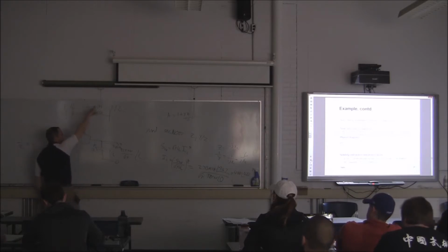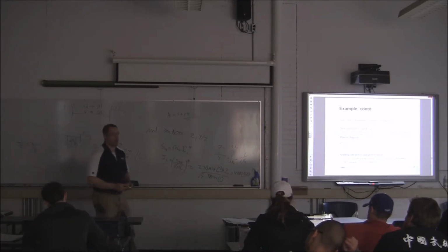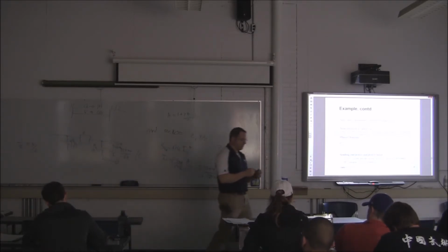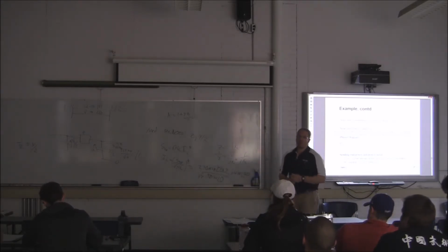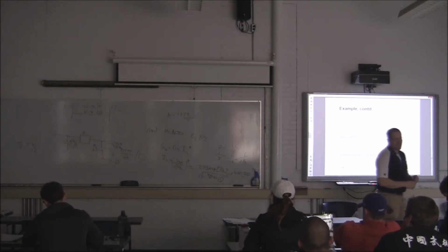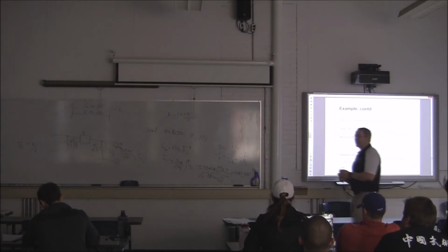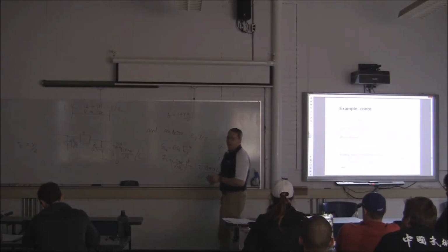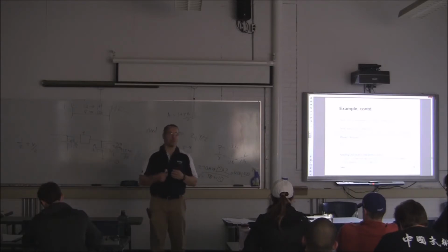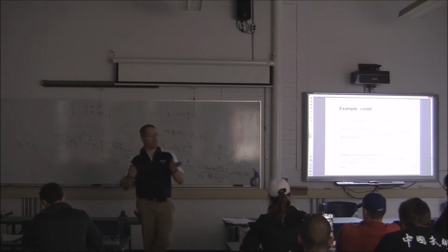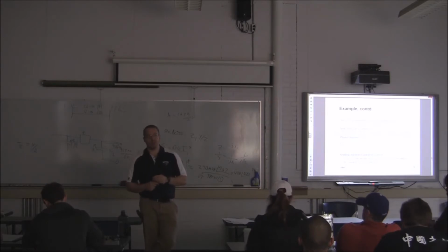So if this angle theta is higher than this angle, then what does that mean? Real power flow is from the higher angle to the lower angle. And that's the case when your X over R ratio is sufficiently high in your system, which almost all real world power systems have. So I could look at a diagram with bunches of voltages on it, and I can tell you just by looking at that diagram where the power flows, both Q and P, just by looking at magnitudes. I don't even need you to calculate the P and the Q. I can figure out overall directions just based on that.